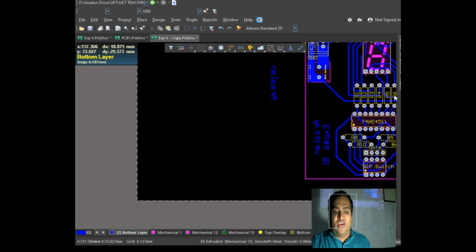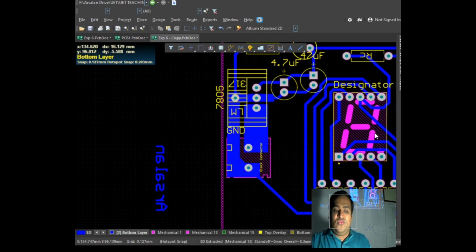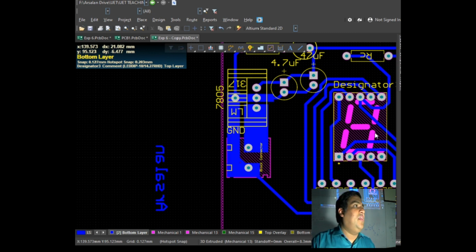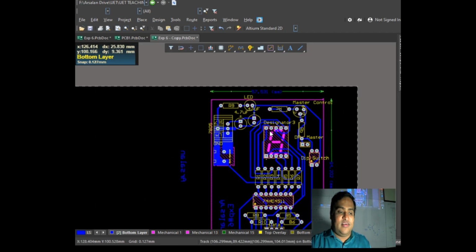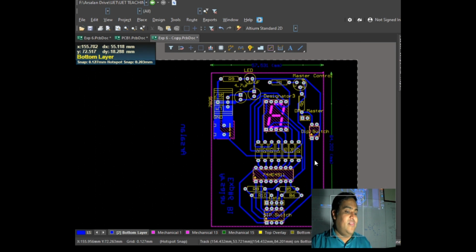Now these tracks which are connected from one resistor to the 7 segment, there is no need for any fill area. They are very simple. They do not carry that much current. But yes, when you move towards a yellow dot matrix or an RGB dot matrix, then certainly we will ask you to increase the track size. But overall, as far as this is concerned, this PCB is going to be designed in such a way.